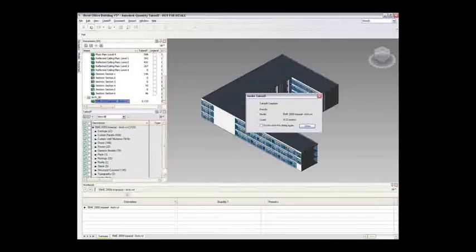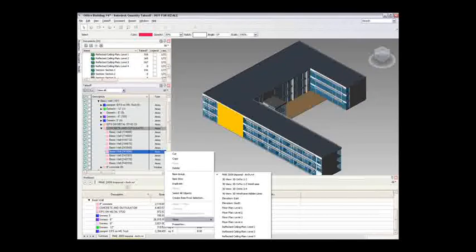Like I said, it gives you different techniques. And one of the things, which I didn't show you, is that if you highlight an object that's already been quantified, you can make it visible in any view that is available. So if they send you the ceiling plans, the elevations, the 3D, it's going to list it just like you see here, so you can track and make sure that that's the right component.